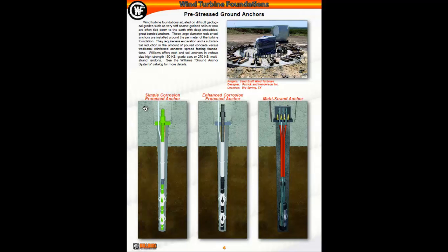The different methods are, you can see these are filled with grout, and as they tighten these threads down, just like any type of anchor bolt, these sleeves actually expand out into the mix and give it more holding power.